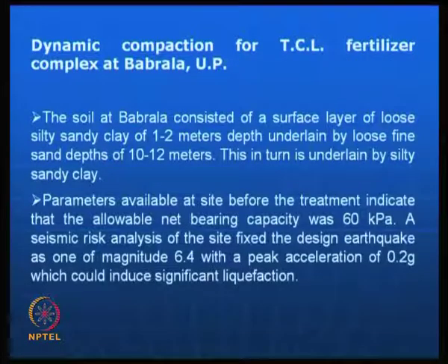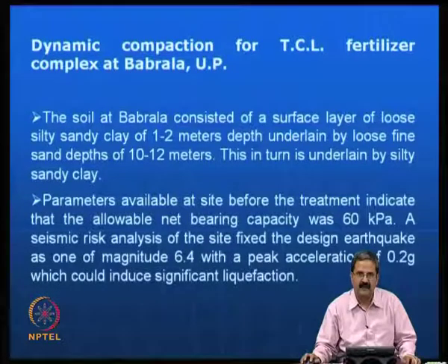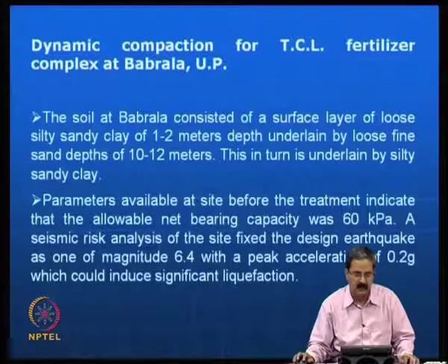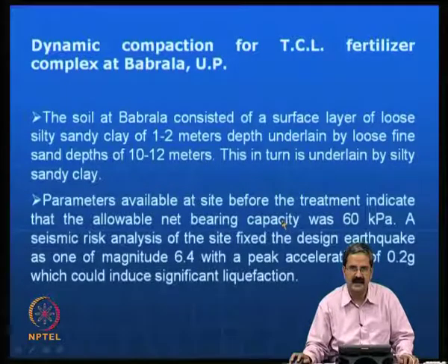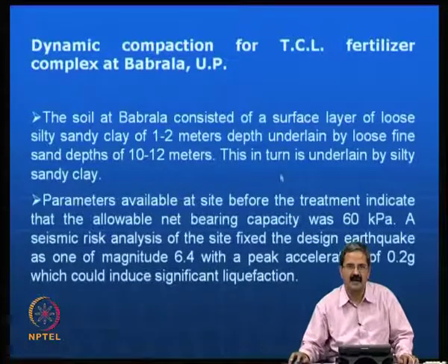We will take up one more case study on dynamic compaction. This is a case study from India, for a fertilizer plant at Babrala, UP. A ground improvement technique using dynamic compaction was required. In this area, you have a surface layer of silty sandy clay of about 1 to 2 meters, beneath that a loose fine sand of about 10 to 12 meters, and again a silty clay.